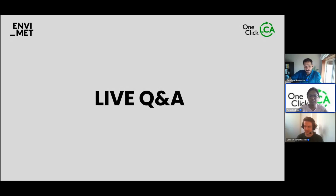So the first question we have is from Manohar. Is it a continuous assessment tool for all seasons? No. ENVI-met is considered to be a tool used especially for heat stress events. So for summer season, it is best suited. You could also use it for spring events and also autumn events. I wouldn't recommend using it for winter simulations. There's not a lot of point in that. So it's mainly used. It's really good at heat, basically.